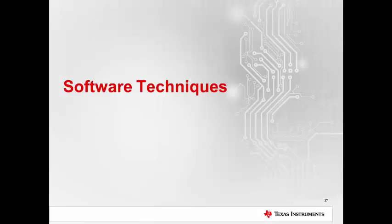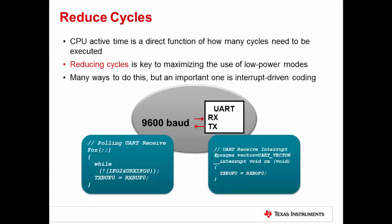We have discussed many of the features and benefits of the MSP430 architecture, but as mentioned previously, good software is just as important. So let's take a look at some software techniques to reduce power consumption. The first thing to remark is the importance of reducing CPU active time. As mentioned previously, the more cycles we can reduce from the CPU, the more time we can stay in low power mode. An important method to do this is by using interrupts.